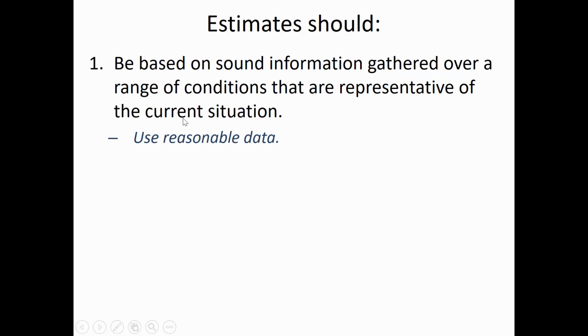So for example, if you're trying to estimate the cost of a structure in Alaska, the conditions in Alaska are very different than the conditions in California. And so if your company previously has done a lot of projects in California and you know how much it costs to pour a concrete foundation in California, then it wouldn't be reasonable to try and extrapolate that cost data up to Alaska, because those conditions aren't representative of the current situation.